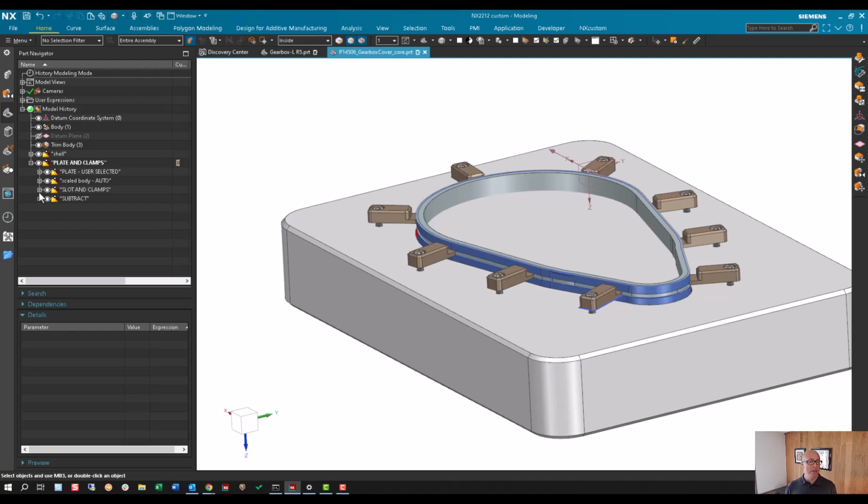It can just be the way you extrude, and maybe you capture, when you extrude, some important datums in your design, and those are part of your company standards, so that you can constrain to those datums, which makes your designs more robust. If you have different reference sets and things are disappearing, you can ensure those datums are in all reference sets.